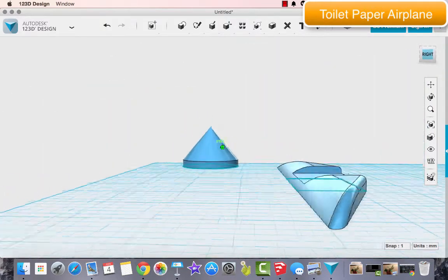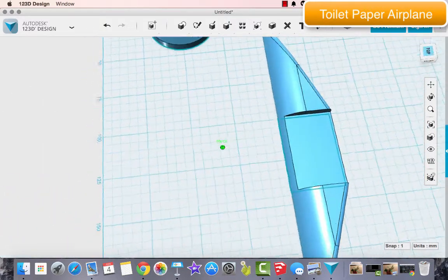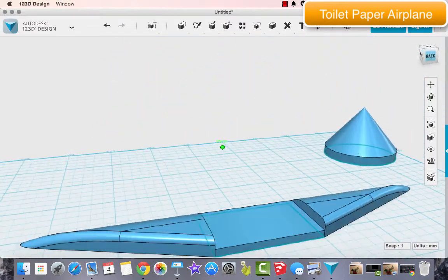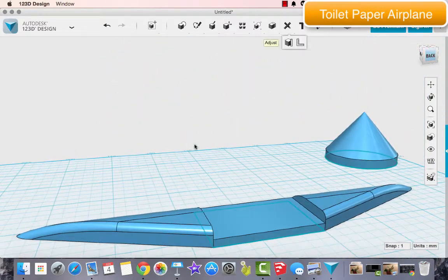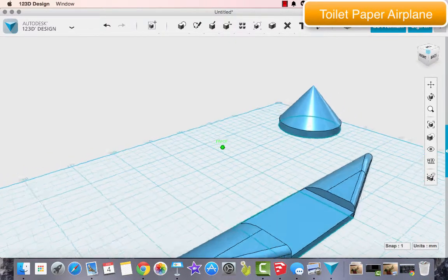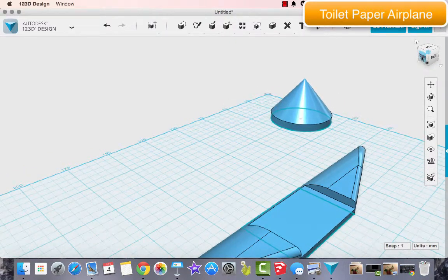Still a little bit thick, but that may work, it may not. That'll be a nice part to test out with your students. It's got a slight curve in the front. It's got a nice round to the back to be able to slope down. We want that air to be able to swirl over. We want it to be able to travel more on the top than the bottom. If that happens, then we generate lift.